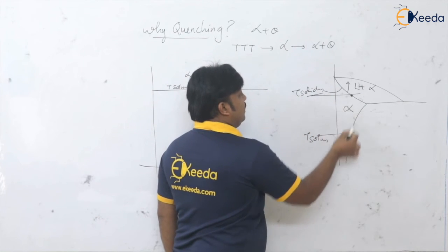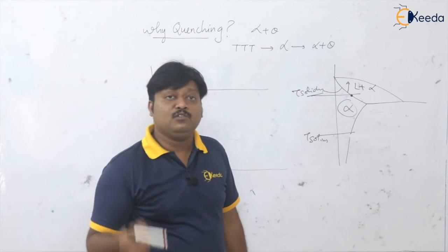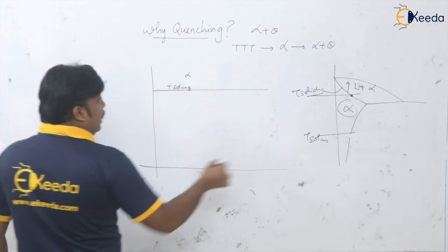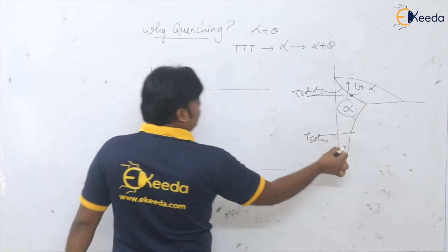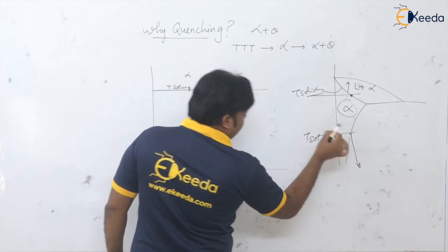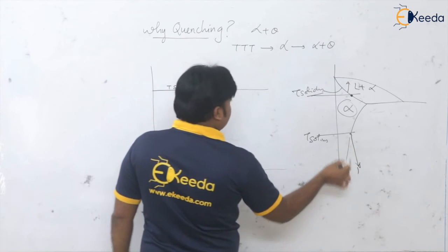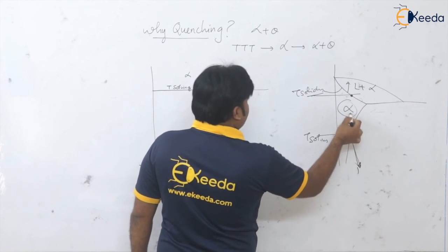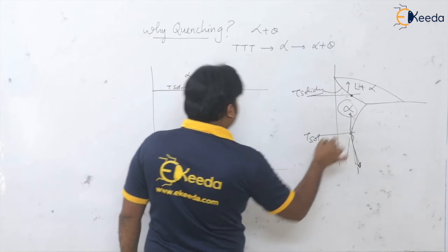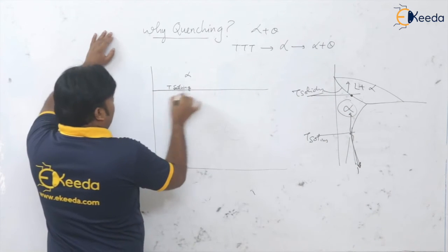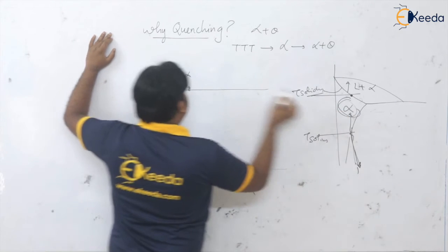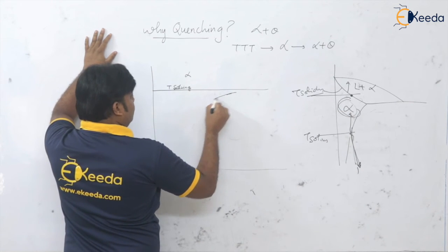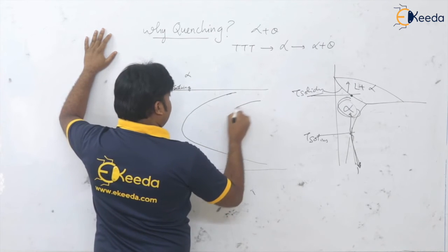Please keep it in mind, because heat treatment is always done in the solid phase, on the shaped object. That is the reason. So we are cooling it below this solvus, so it stays in the solid state. Above this, everything will be alpha. So this is alpha, and when we cool, we get this C curve.